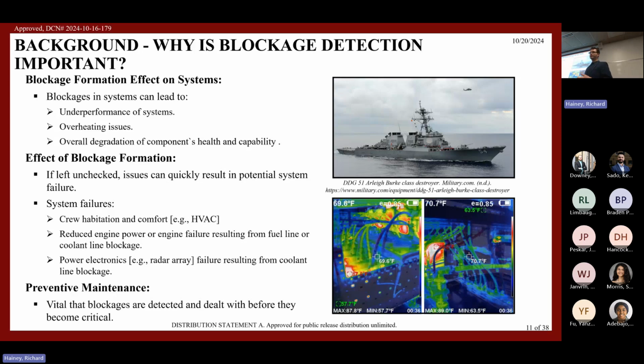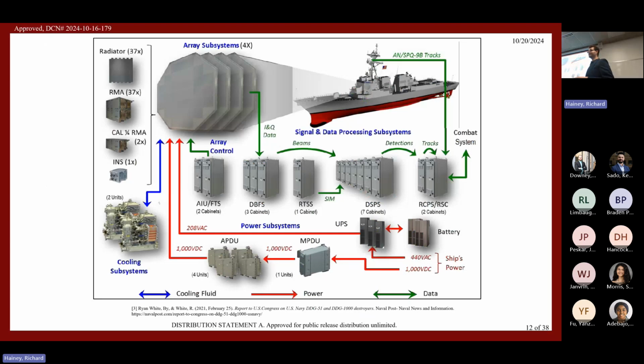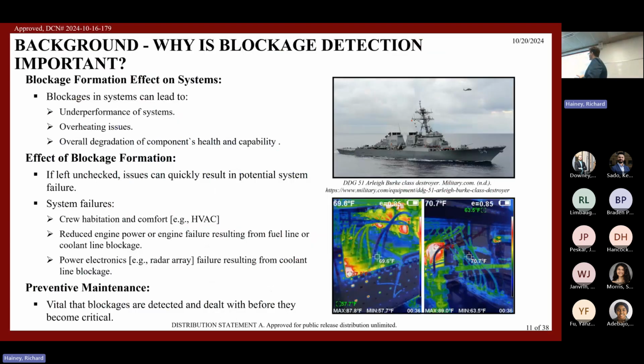So we ended up fixing that just by flushing the system, adding a new filter, and changing our system from tap water to distilled water after it happened again. So this is what set me on the path of my research, essentially, because then I spent the next year studying blockage formations and their effect on systems.